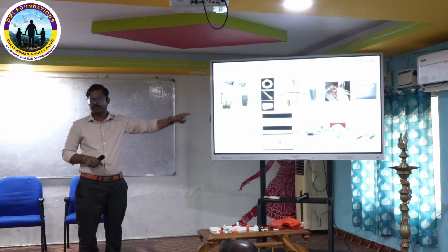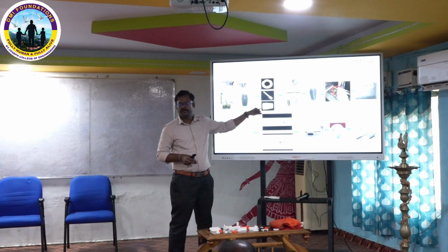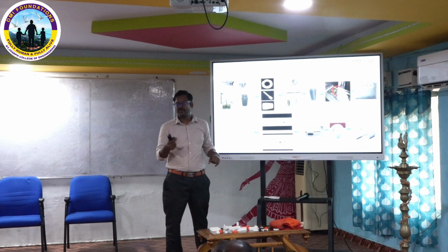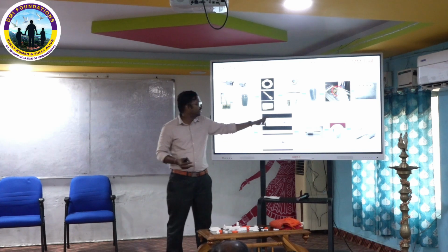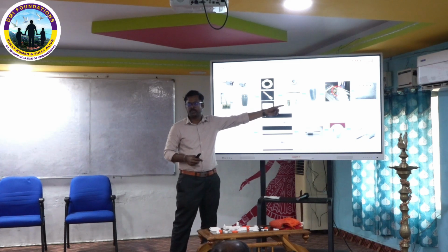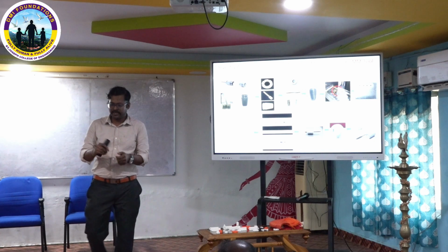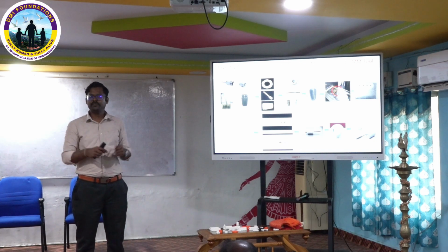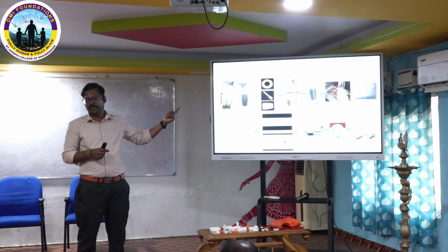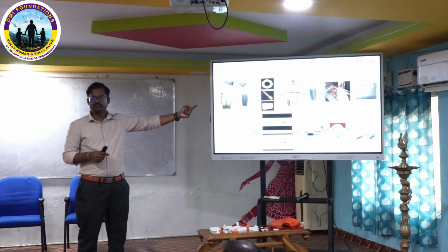on the machine and fabricated it. I also faced one problem: the collet, which directly holds the tool, has a minimum thickness, and during the coating it broke. So I redesigned it. It should hold the tool when tightened, and at the same time it should not break. Like that I did 3 to 4 iterations and finally came up with this design and completed the work.